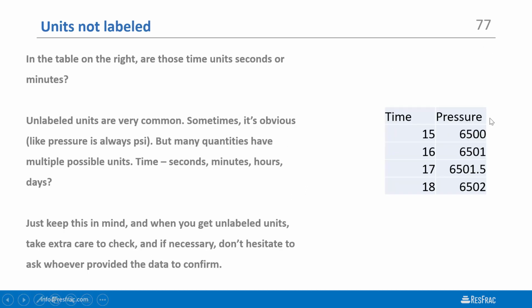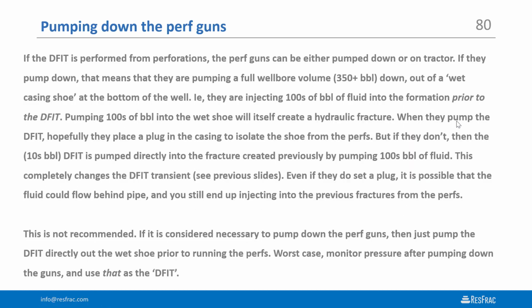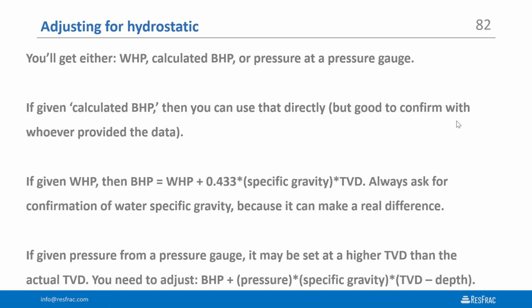Another example here is I've got pressure. Is that wellhead pressure or bottom hole pressure? And not just bottom hole pressure, but if they give you bottom hole pressure, where was the pressure gauge actually set? Because bottom hole pressure doesn't always literally mean bottom hole pressure.